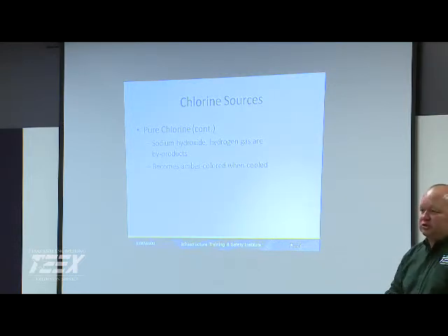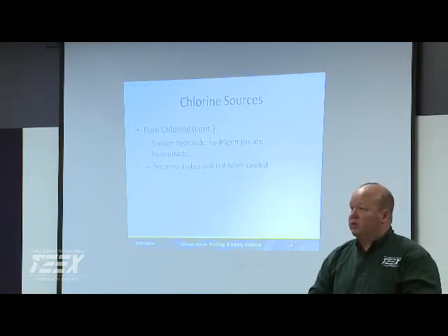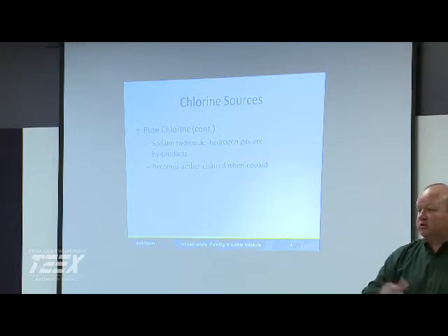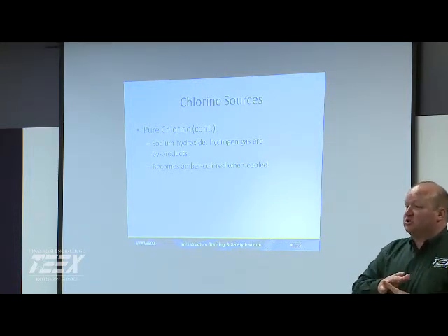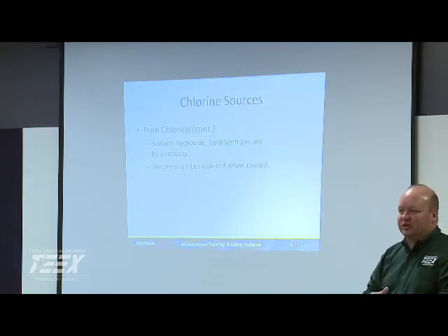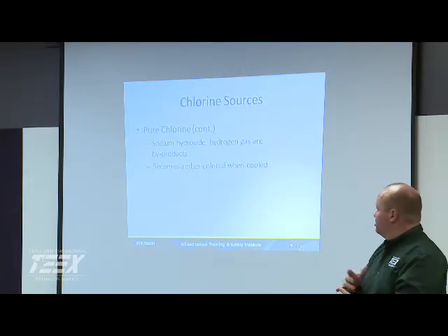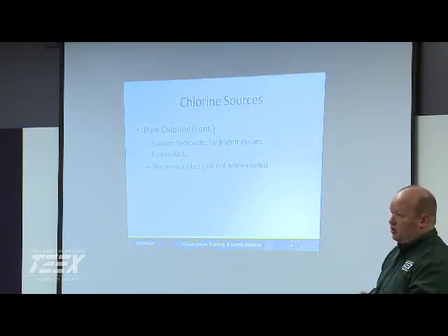They mentioned there was an explosion a couple of years ago in one of the locations here in Tennessee. Somebody lost their life, because it wasn't properly ventilated, probably wasn't cooled properly. You start to produce hydrogen, and obviously you've got a lot of electricity in the building, a bad environment. So those are things to be really careful of or consider when you're looking at alternative methods.